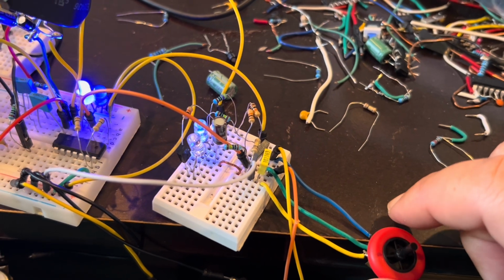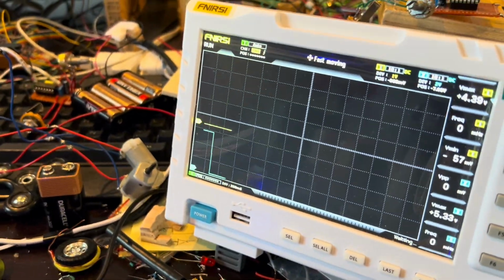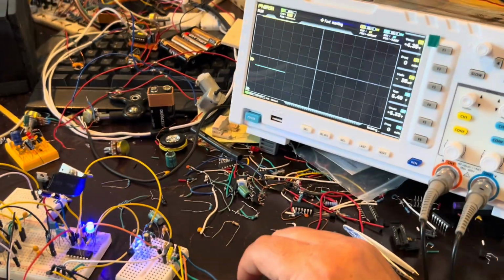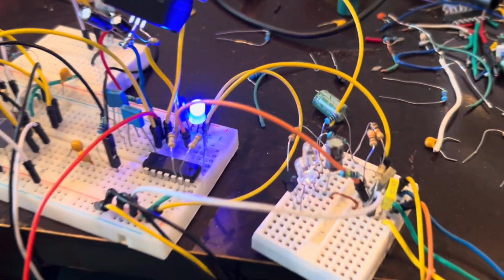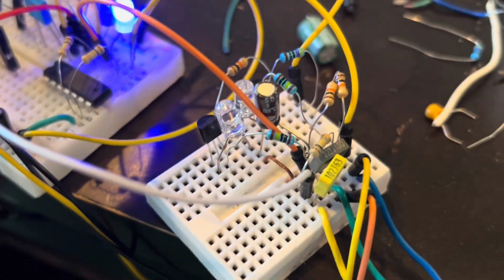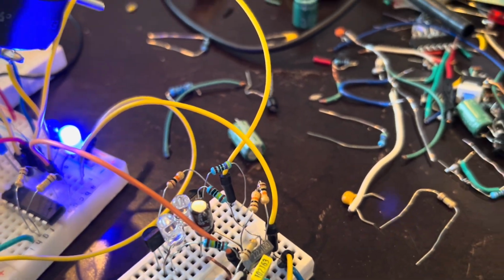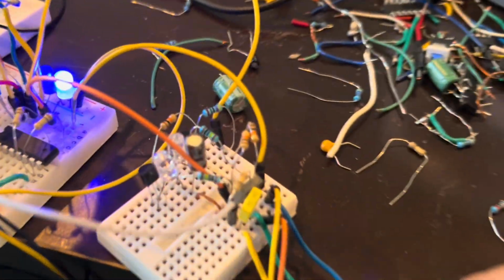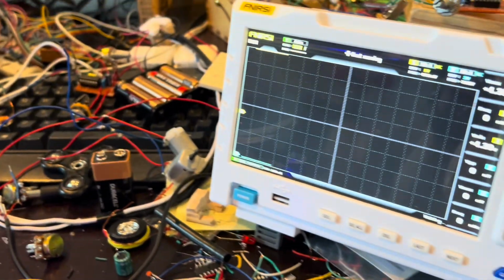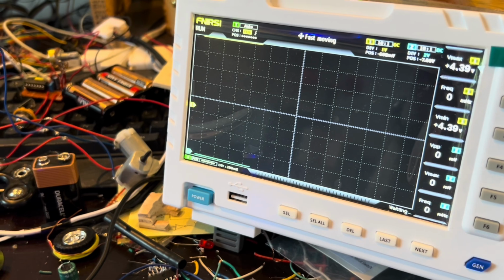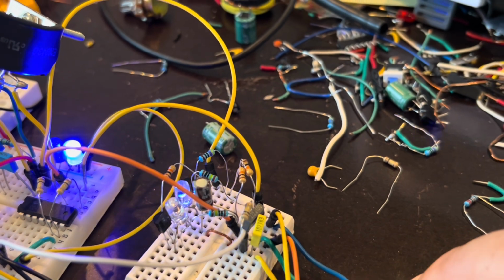I'm going to show the schematic for this too. And once again, the clockwise mode and the counterclockwise mode, I'm going to show on the oscilloscope. So the clock pin, which is the B pin, which is the left LED light, goes on first while the A pin light goes off. So I'll show you that here. This is turning counterclockwise, and see, that's off, and you can see the logic levels on the oscilloscope. And then finally it turns on, and it keeps on turning in that direction.